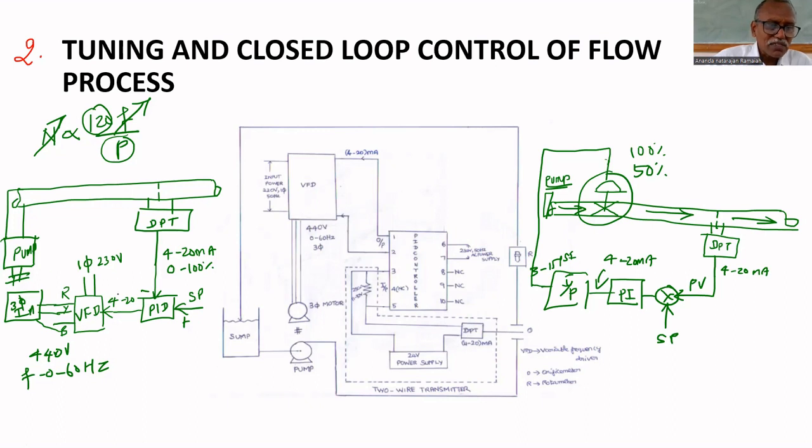In our lab, we have this type of arrangement, not valve. But in level process, we have valve. There also we can put VFD. This arrangement can be implemented in level process also. But in most of the industries, they will use valve. Nowadays, it is gradually changing to VFD.